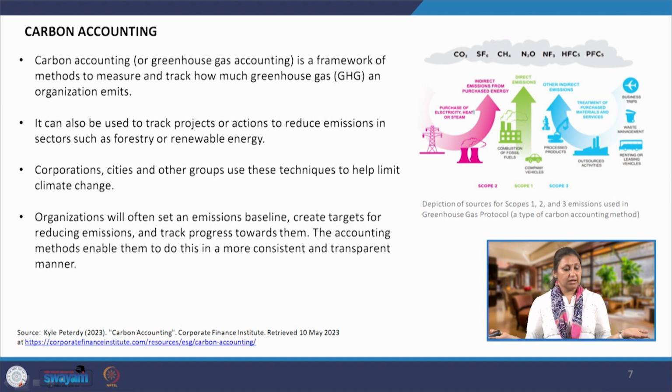We have to do the carbon accounting, carbon footprinting of both these buildings. Both are buildings, both are serving probably the same function. So, there are two parts. One, how much carbon the manufacturing or construction process for this material, which is say mud, has produced versus how much carbon dioxide has been released during the production of glass as a material. That is one. Two, when we are occupying this particular building which is made of thick mud walls, what kind of indoor environment is there? How much energy do I consume when I have to maintain a comfortable environment inside is also a part of it.